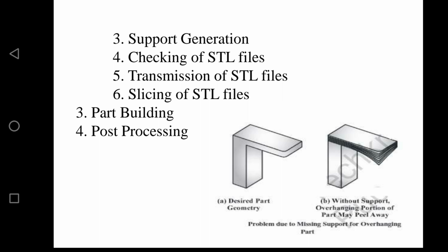Next, the final part in your pre-processing is slicing of STL model. Okay, so the pre-processing software on the rapid prototyping machine computer slices the STL model into a number of layers of varying thickness, like 0.1 mm to 0.5 mm.